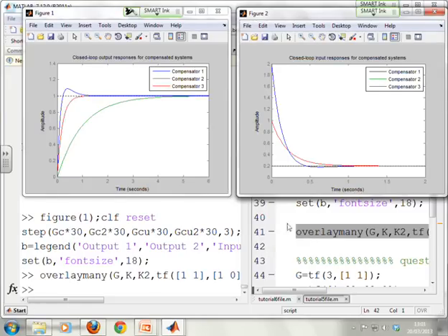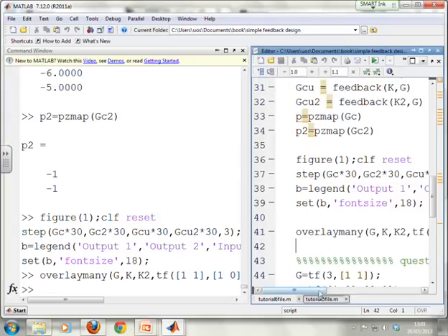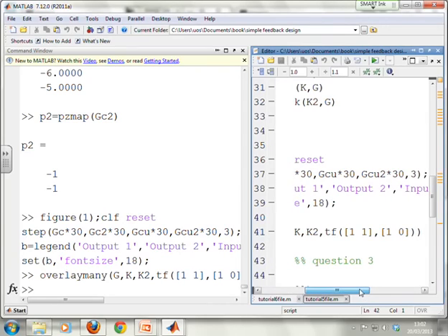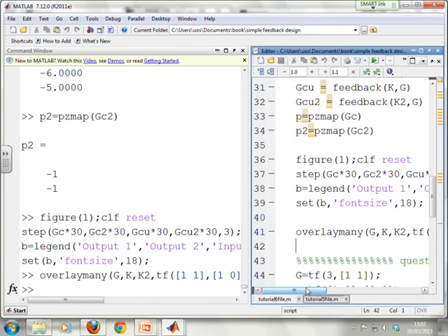So there we go. You'll see I can very easily get a compromise between very fast, the blue, quite slow, the heuristic, and you see the red is this compromise compensator. And if you look at the inputs, you'll see the heuristic steady the whole way through. The red starts at 1, so it's 5 times more aggressive, and the blue 10 times more aggressive. So I can easily explore with Matlab what happens as I change compensation just by sticking all these K's in here and tweaking things a bit, and therefore fine-tuning starting from a controller which is reasonable.